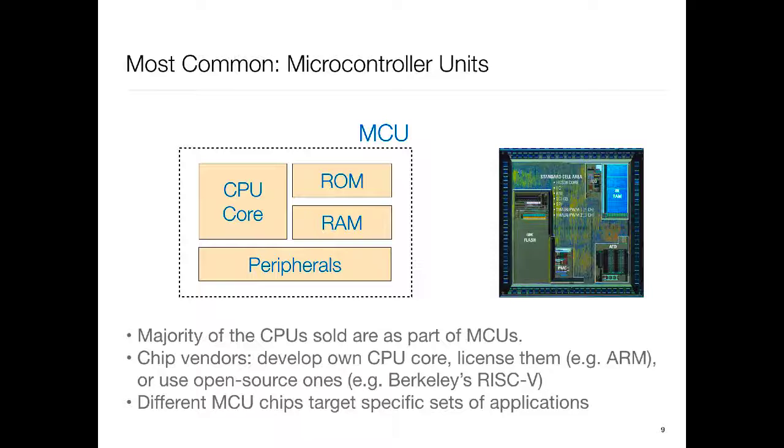And there's a whole bunch of MCUs. If you go to any of the companies which make these MCUs, you'll see that Intel may sell, I don't know, maybe on the order of 10 variants of the microprocessors at any given time, whereas these companies will probably have a few hundred, because remember, you also have ROM, RAM, and peripherals. So they sell different variants of these MCUs with different amounts of RAM, ROM, to accommodate different cost and power budgets and different types of peripherals. So there's a rich menu you will find, and you go and select what you need and go with that.